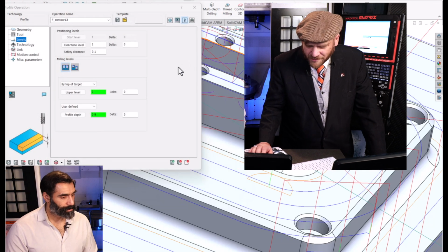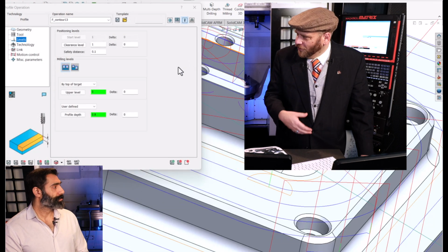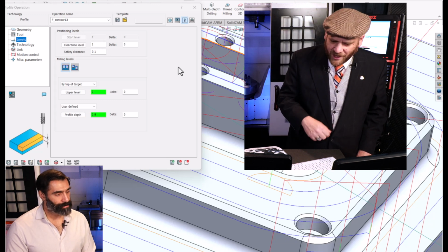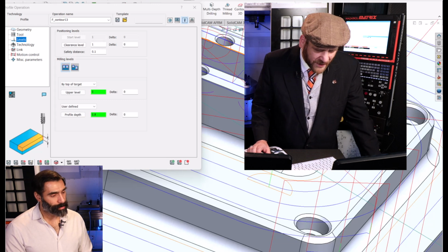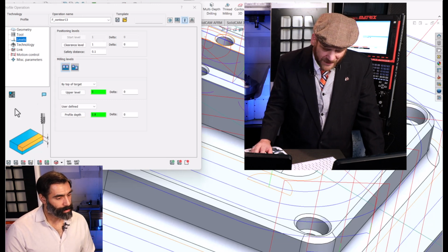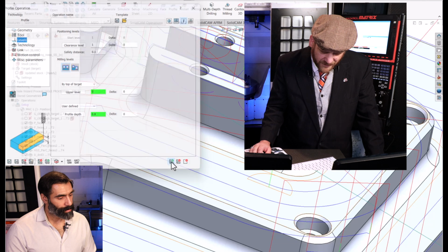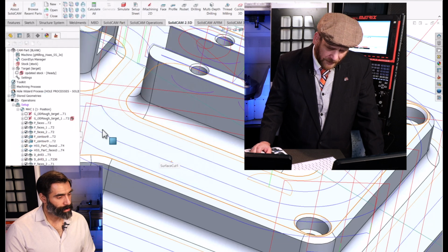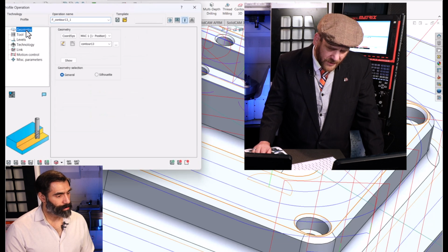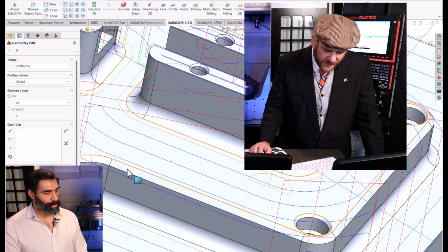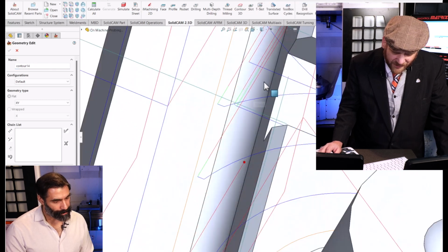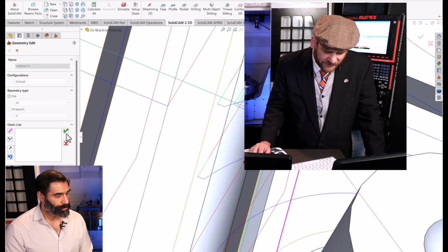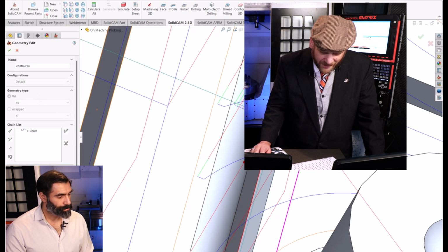And I'll do one more operation for you because everything else is just repetitive, me drilling holes and checking things again and again. I'll use that spot drill to cut the chamfer. Okay. So again, I'll use just a regular profile toolpath to do that. And I'm going to pick this edge of the chamfer, but it's an open area on the end here. So I'm going to pick right there. And that chamfer is called out in the MBD. I did look at it.